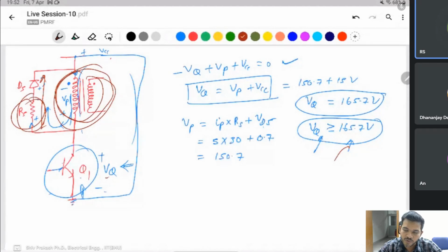You should increase this resistance value to dissipate all the stored energy in less time than before. Like if you have a 0.6 duty ratio and then increase to 0.8 duty ratio, you have only 0.2 of turn off time, and before you had 0.4.